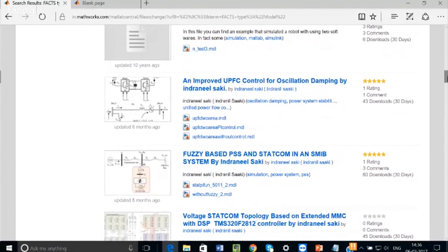One more thing you have to remember: when you download this, sometimes it will not run fully, so you have to modify it. One problem you may face is that some of the systems will be masked. I'll be telling you the concept of mask. In that, you have to set some of the variables, and once you set the variables, your program will run. The other problem is that when you download it, your version may be different. You may be downloading a version 13 model, but your system is version 16. Or somebody has put a version 10 model.